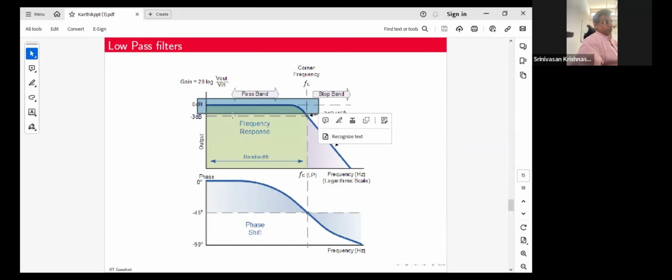This kind of gives you the amplification that you initially have. So the input and the output would have nearly the same loudness. For an amplifier, you would typically want this graph to go slightly higher. But the important thing is that this part of the frequency response is flat, which means the amplitude magnification for frequencies in this range is going to be approximately the same.